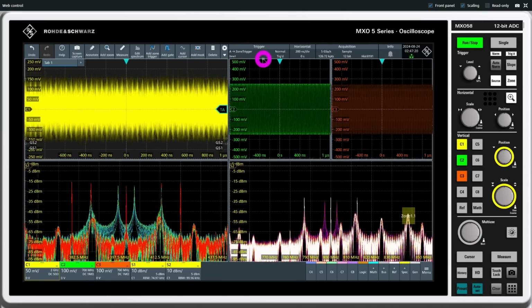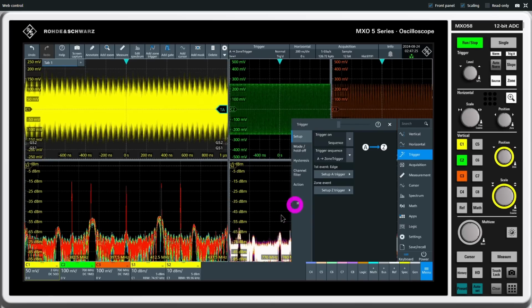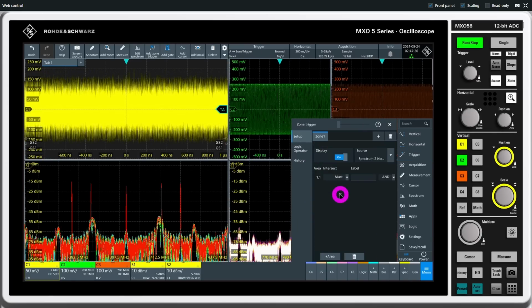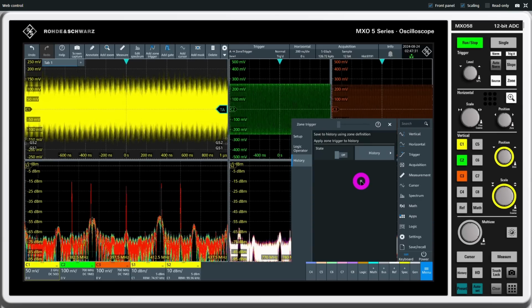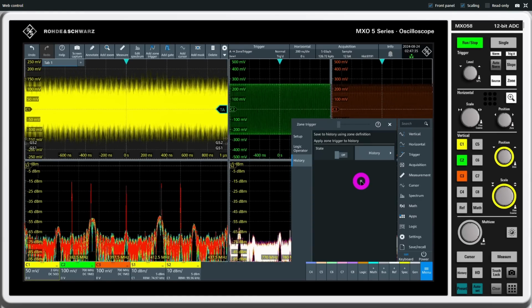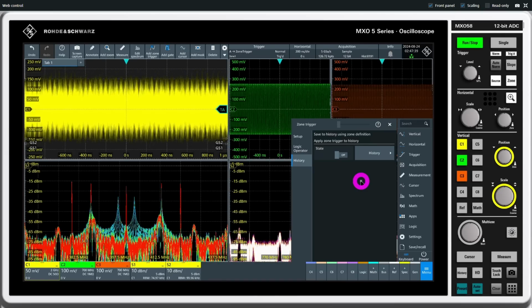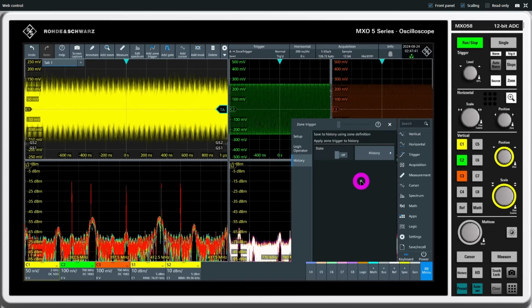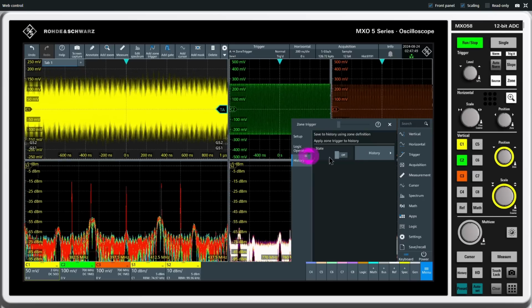And all of these zone triggering that we can apply can be applied to the waveform live, but they can also be applied directly to the history of the waveforms that have been recorded. So you could have had something, you can play it back, you can do your zone triggering on it, and then if you're not happy about it, you just do a new zone triggering on the same waveform. And that can be also pretty helpful, because sometimes an event is really rare, and if you have a window that has that event in there, you can do further analysis over and over again until you find out what it is that you're looking for. So it's pretty good to do this.